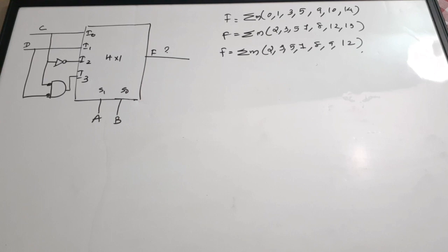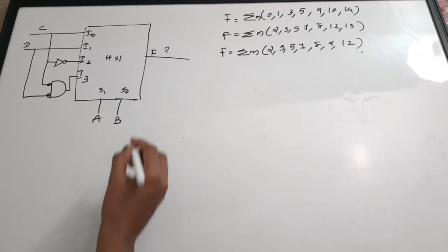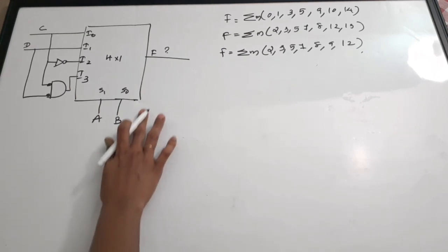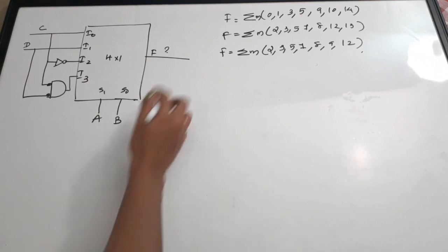Okay, so this is again a 4:1 multiplexer. Most commonly you will only be seeing 4:1 multiplexers, and there are two other gates also connected to the input side. There is one NOT gate and also an AND gate with two of its inputs complemented at the input side. Okay. Now what is the expression? I'll write first the logical expression. Here I'll start writing from here.